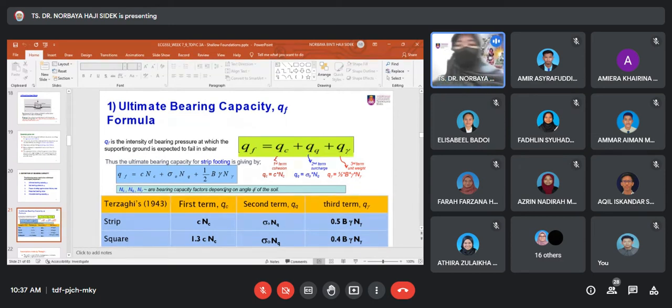So for the bearing capacity factors, there are 3 different ways to get these values. First, the values of Nc, Nq, and N gamma are given in the question. So if they give you some case, it's given to you that Nc equals 37, for example, Nq 28, N gamma 36. That means you just use whatever values are given to answer the question.